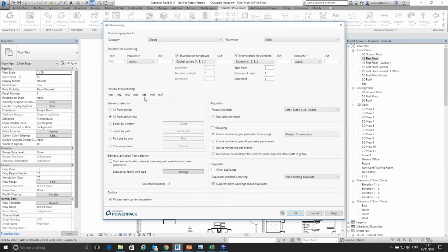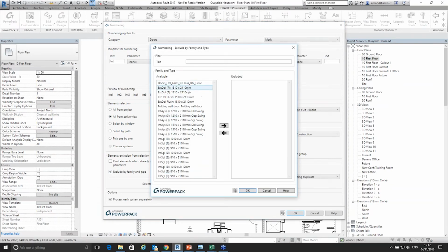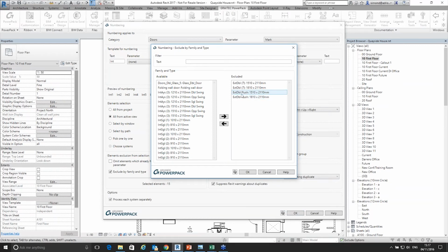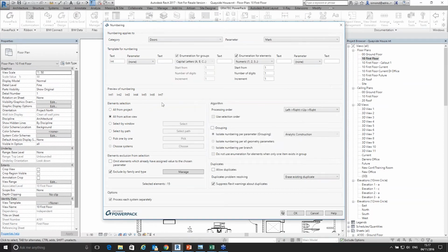So if I actually had numeric, I could set that to 001. And we can start to look at setting up what the increment digits are. It'll increment by 1, and the increment is 1 as well. So there we go, increment digit 2. If I wanted 3, that'll give me doors 001, 002, etc. I could even say I want to increment that by 10, and then it will keep the 1 from the first one because my starting character is 1, and it'll add 10 to each of the doors as well. So the sequencing and the way that we can work in here is incredibly powerful.